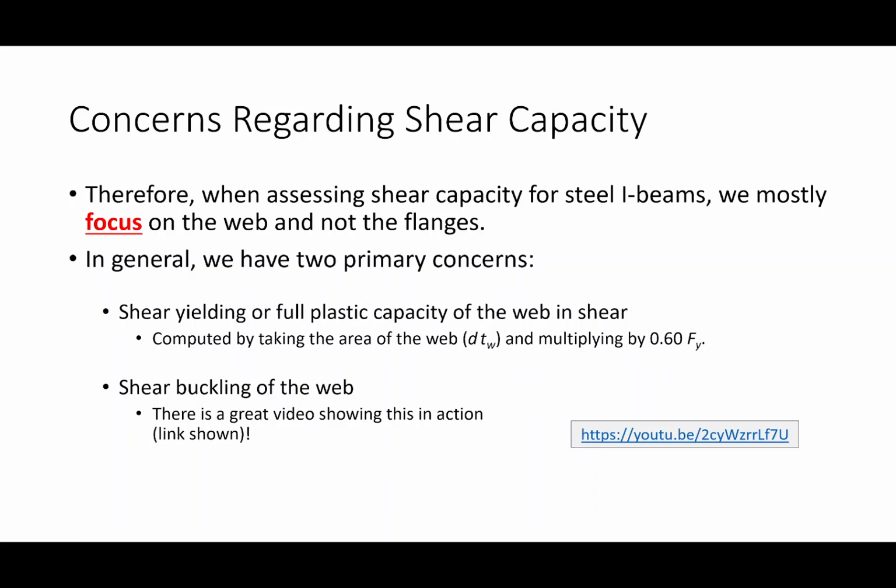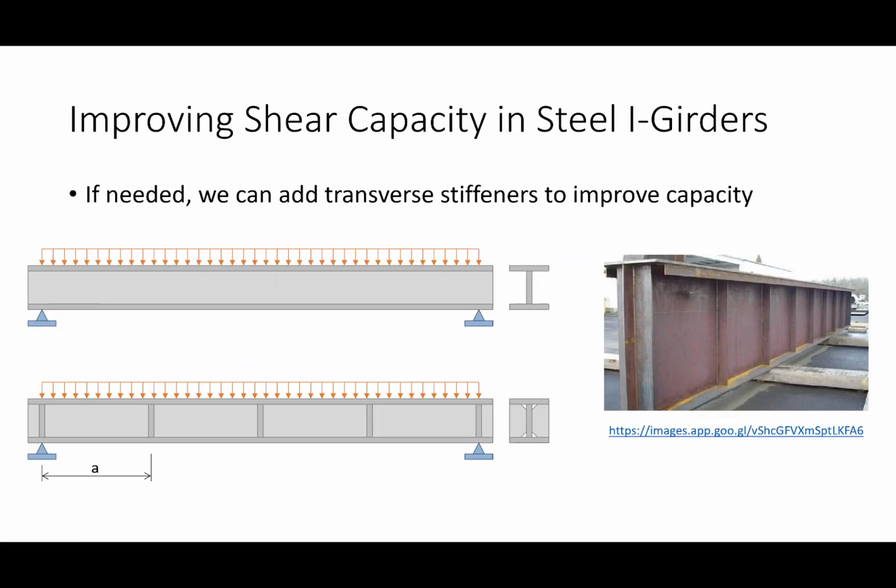But if you look at a concrete element, so if you look at concrete design, like here's a concrete beam, and you load it in shear, you get a crack that looks something like that. Because what happens is concrete is in compression this way, tension this way. Concrete does not like to be in tension, and concrete cracks when it's in tension. So when you load it this way, it cracks. So shear, 45 degrees, there's an analogy there. Okay, make sense? All right, let's talk about the spec.